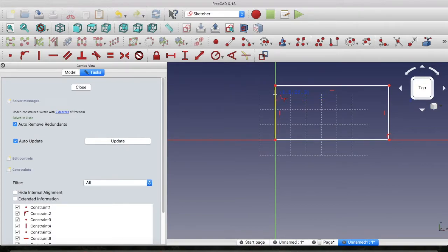Important point to note, you must always ensure that the line diagram of your sketch is fully closed, failing which you will not be allowed to move forward in making the 3D object. This is very, very important. Press the Escape key from the keyboard to come out of the polyline command. The cursor takes back its arrow shape to accept the next command.